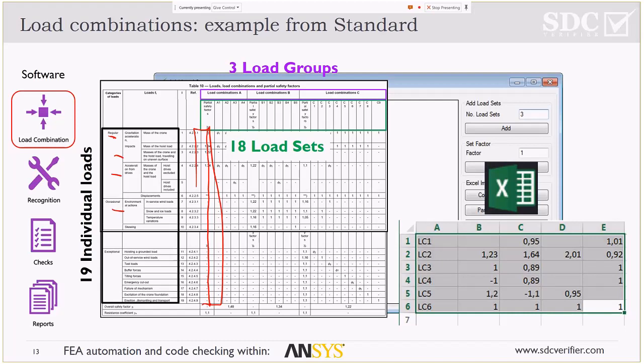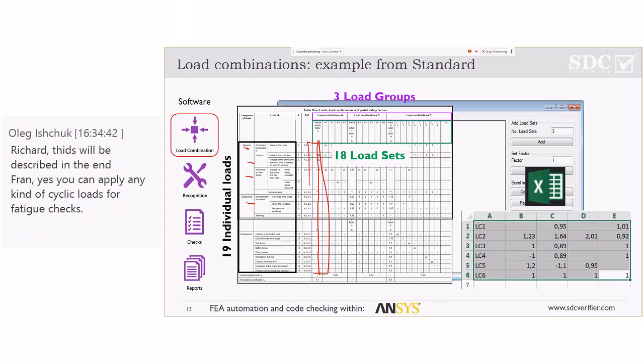And the other thing is you need different load sets, for example, operational conditions or operational conditions with wind. Or if you do the maritime equivalent, you have the still water conditions, the operational conditions with wind and waves, and then you have survival conditions.